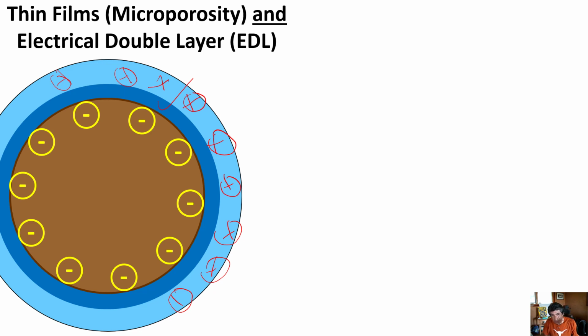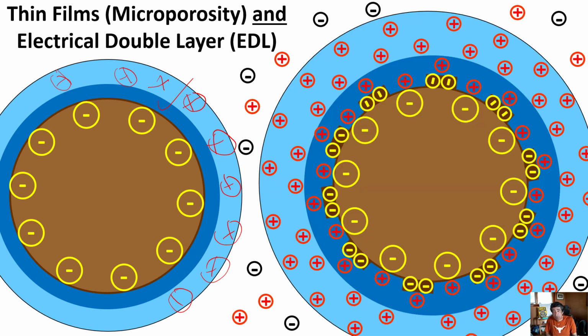Of course, the attraction will depend on several things. But clays have a very high surface to volume ratio and a very high negative surface electric charge. So the attraction of the cations is potentially very large. And that attraction generates a cloud of cations surrounding the clay minerals.